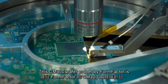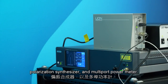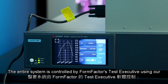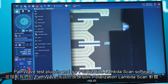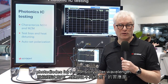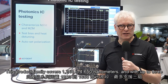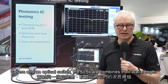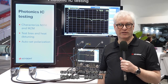This CM300 wafer prober by FormFactor is equipped with a Keysight tunable laser, polarization synthesizer, and multiport power meter. The entire system is controlled by FormFactor's test executive using our Pathwave test plugin and our polarization lambda scan software. By swapping the power meter for a source measurement unit, we can test photodiodes for responsivity over wavelength. This product family covers 1240 to 1650 nanometers, and with up to 3 lasers and an optical switch, the software combines their wavelength sweeps into one trace.